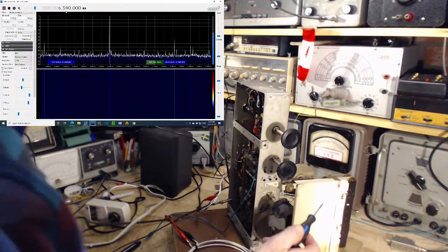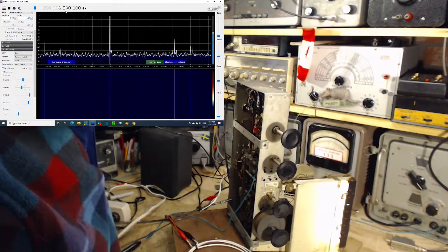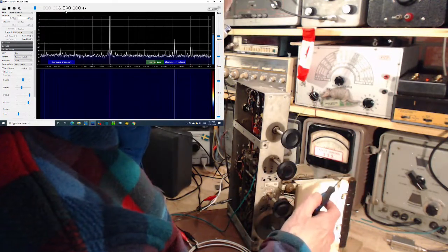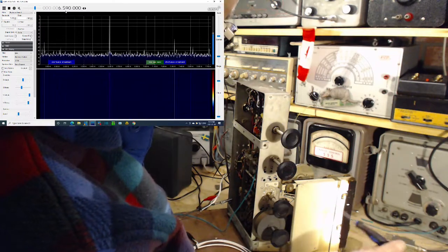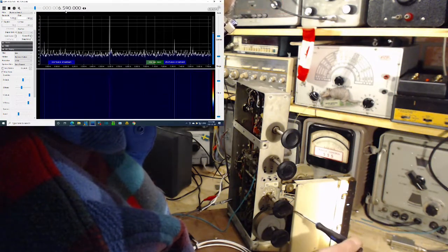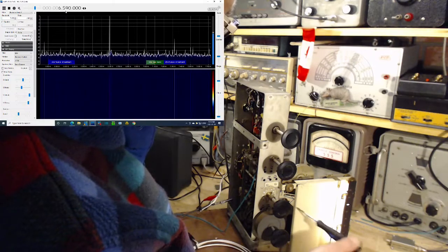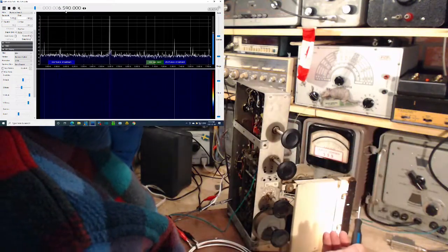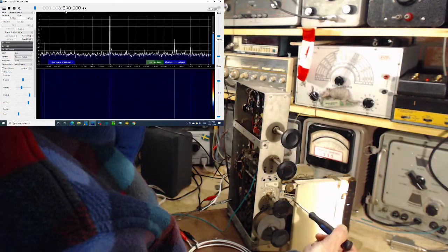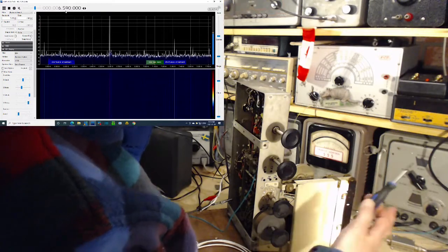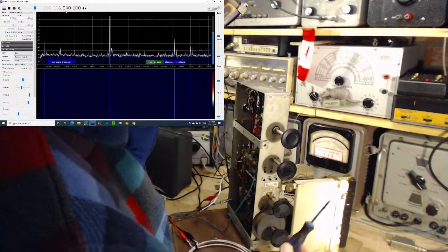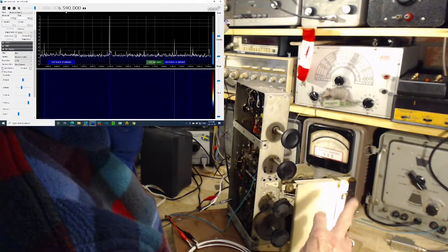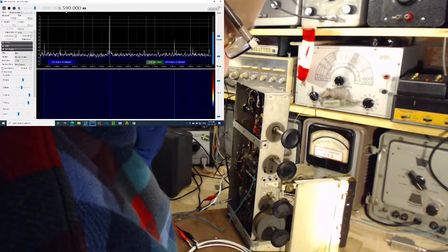You know what? There's a bigger logical problem here. As soon as I made adjustments down here, that caused the other end to adjust a little bit. As soon as the other end adjusted, my original numbers were no longer valid. When I came and set this to my original numbers, they were no longer valid. So everything I'm doing here is not valid. Everything I'm doing is going down the drain, and it's because there's 2 controls. If there's just one, I can get away with this technique.